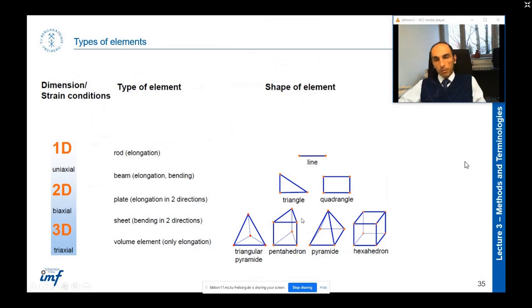Of course, in the case of 2D, when it's a quadrangle, it's more stable and the calculation is simple. But if your geometry is complicated, you cannot use it, because you should break it down into small pieces and this is the only form you have. Usually, when your geometry is complicated, you cannot use this one. Then you should use the triangle elements, which are more flexible.